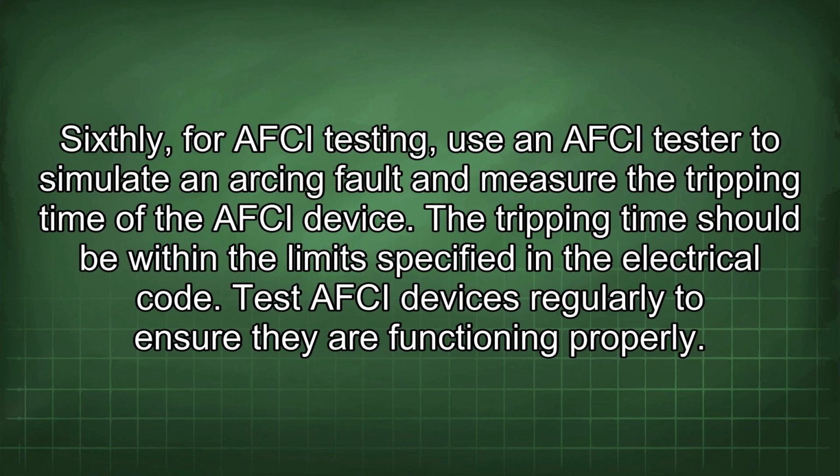Sixthly, for AFCI testing, use an AFCI tester to simulate an arcing fault and measure the tripping time of the AFCI device. The tripping time should be within the limits specified in the electrical code. Test AFCI devices regularly to ensure they are functioning properly.